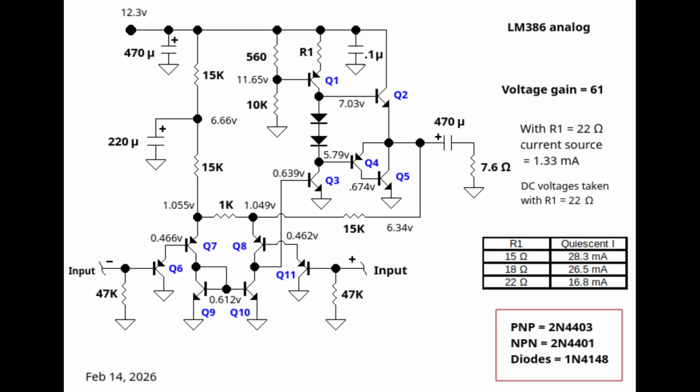The entire input stage functions as a current amplifier. Essentially, the input stage subtracts the negative feedback signal from the input signal, and the voltage difference between the input and the negative feedback arm results in an output current to drive Q3.